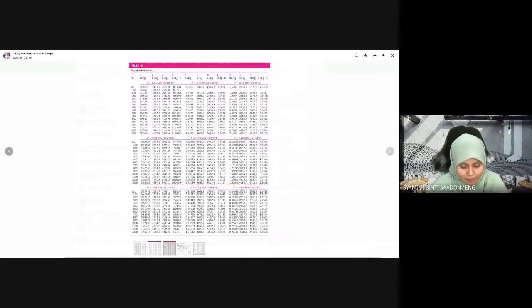So we know that the pressure at state 2, or final, is still 300 kilopascal or 0.3 megapascal. So we look at this box, only this box. And so 300 and then H2 2865. Okay. So we get the enthalpy.